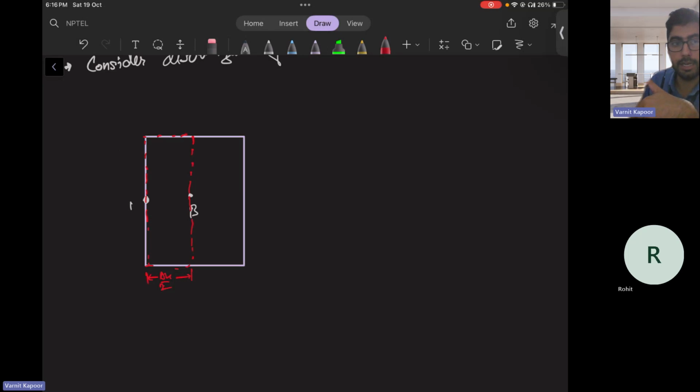So you can see we are not taking the centroid at the cell center. We take the cell like this in order to derive an equation about pressure and velocities on the boundaries, which is needed to update the pressure.